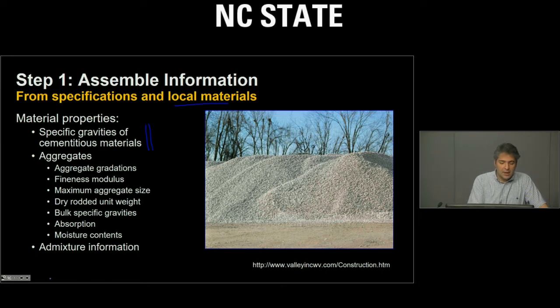Aggregates are very important at this portion of this course. You're familiar with how to measure many of the properties of the aggregate. So we need some of this information for concrete mixture design, for example, maximum aggregate size, dry-rodded unit weight, and all of those. And we want to know the absorption of the aggregate at SSD condition, for example, and the moisture content of this aggregate when it goes inside the mixture. In addition, we want to know additional information if we want to use any admixtures that go inside our mixture.